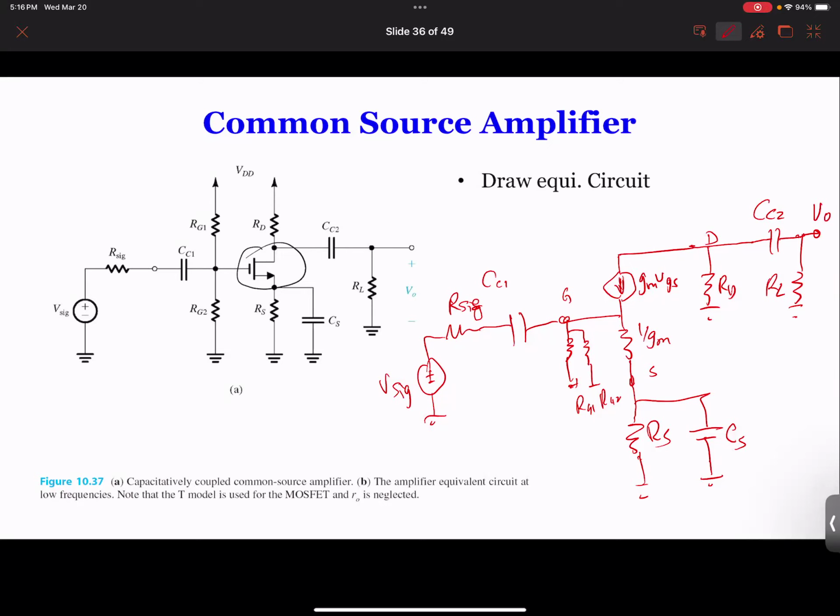So now we got this circuit. And this is very critical for you guys to know how to draw this. And this will be tested again and again and again. So I want to write this in your brain, saying, okay, this is how we do it. You got to understand the process and eventually how to draw the actual equivalent circuit. Basically, you start with the three terminals. This is the T model. You can draw the pi model, nothing wrong with it, but it will make it more difficult to solve the problem. This T model is easy in this case.